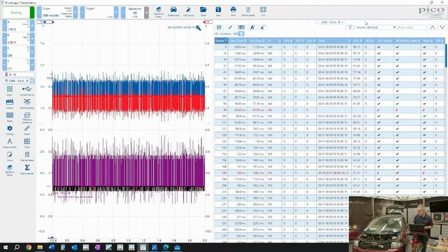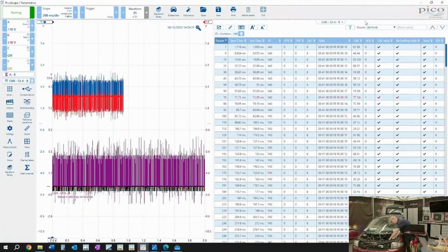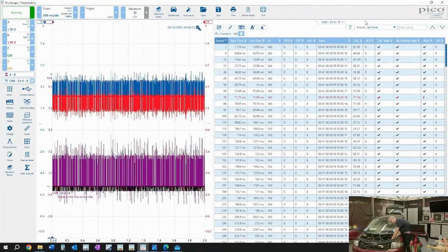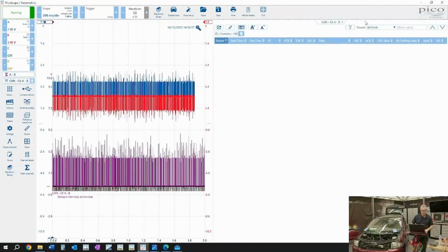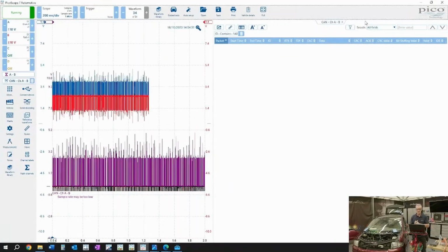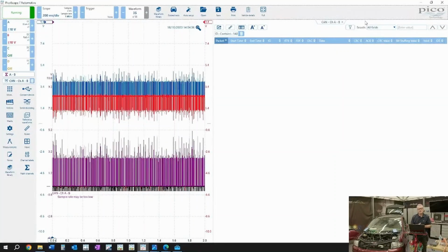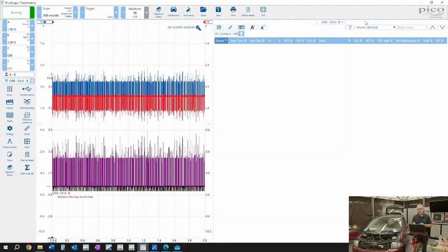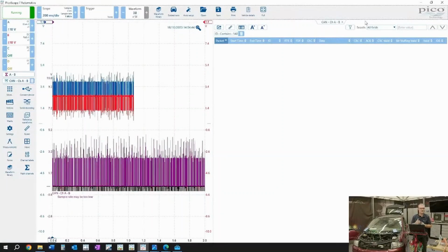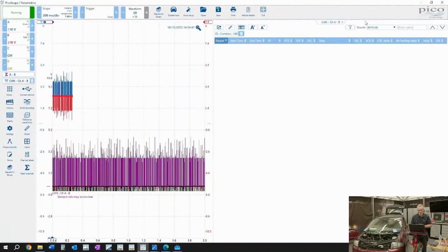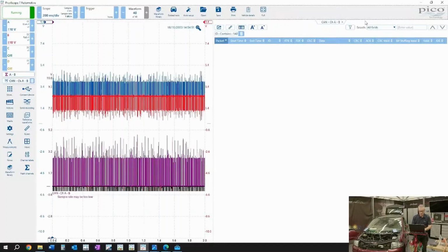So at the moment, 1A0 is present on the network. I'm just going to pull the connector off the ABS ECU. Make sure we've got separation. And now notice, it's not really that clear on the left, but certainly the bus traffic has dropped off. It seems there's less traffic. But now 1A0 does not appear. There will also be other IDs that don't appear, because not only is 1A0 from the ABS, there will be other ones. I think there's 4A0, 5A0, 6A0. Nevertheless, a quick way of determining whether or not 1A0 is online.